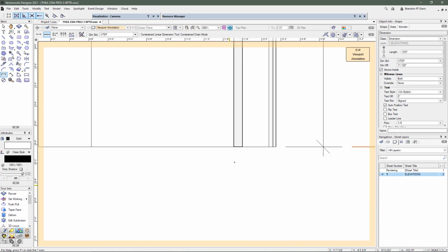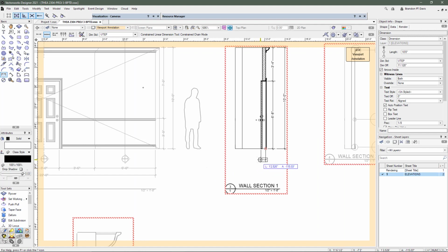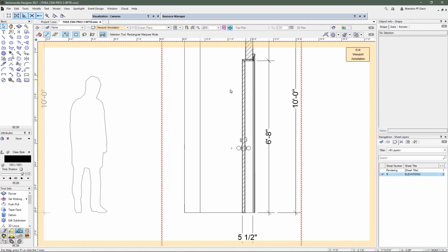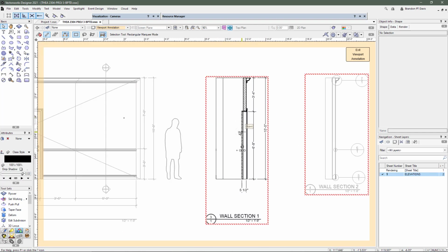And this section's a good place to let the builders know the depth of the reveal in the door. And since they're going to probably buy the door, you don't have to give the dimension of the door. If you wanted to build, I would do a detailed drawing of the door separately.